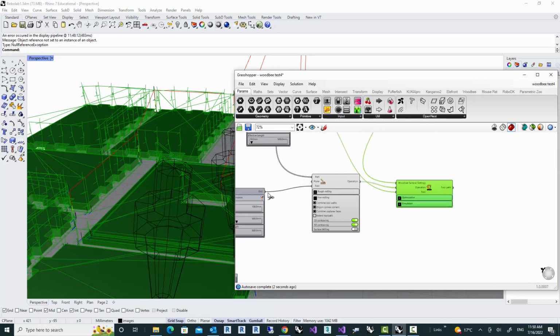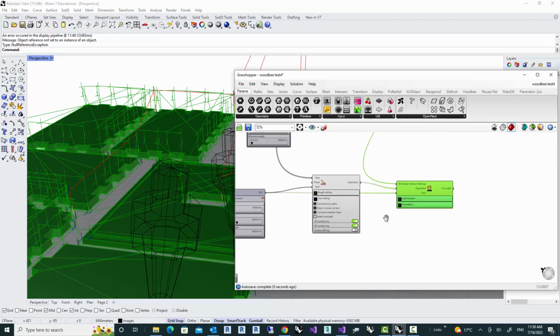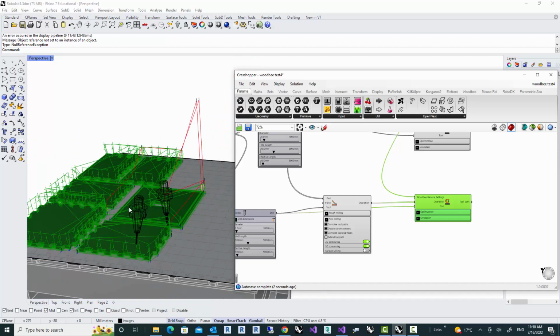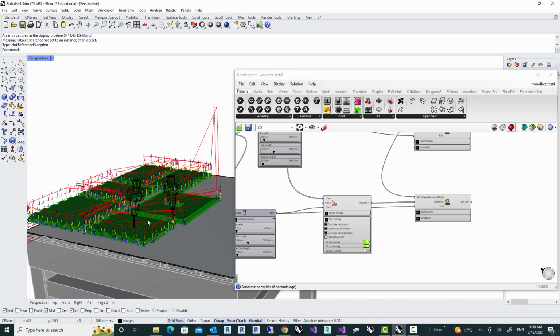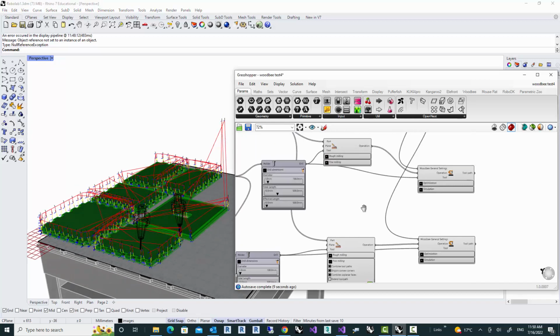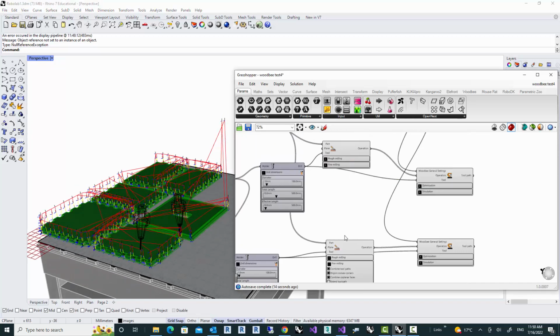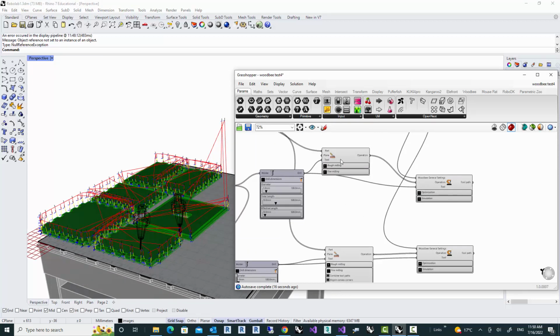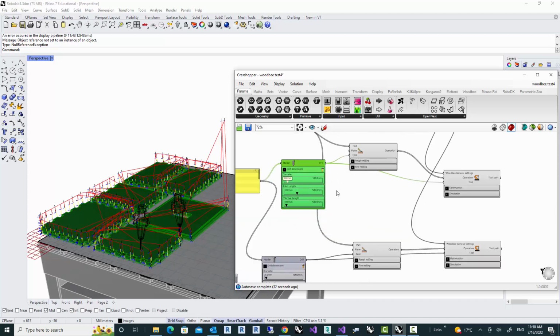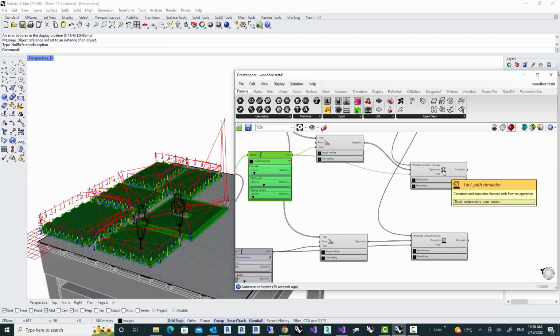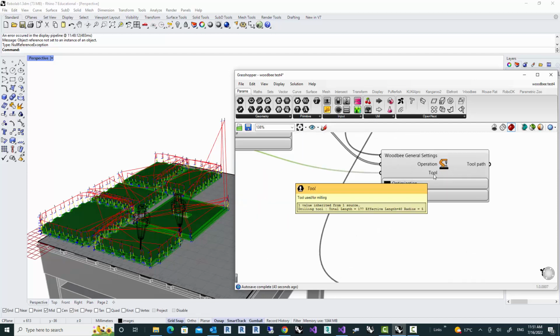All right. So this shows now the entire milling operation that includes both rough cutting and fine cutting. So the important thing is that you need to use a toolpath generator where you have different tools, because each one will accept one single tool.